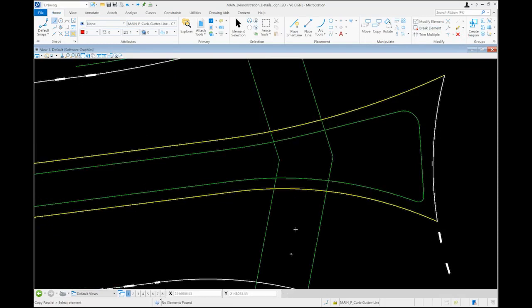Once we have our pedestrian crossing alignment set, we can come back in and do a quick double check on the size of our pedestrian refuge within the splitter island. We need at least 6 feet of width at the narrowest point to make sure that we've got enough room to accommodate somebody pushing a stroller or walking a bicycle across the crosswalk. In this case, we do. We have at least 6 feet there at the narrowest point, so we're exceeding the minimum.